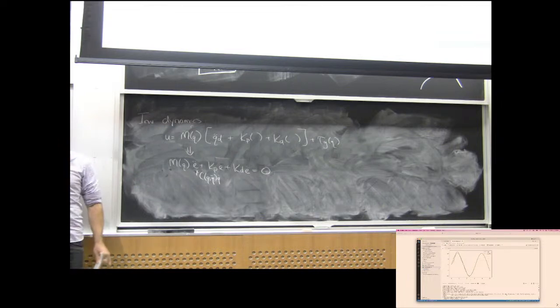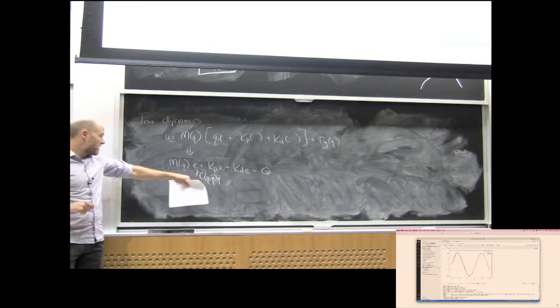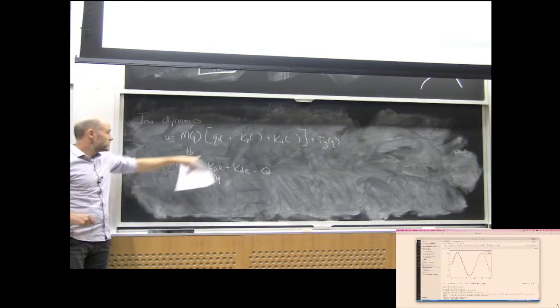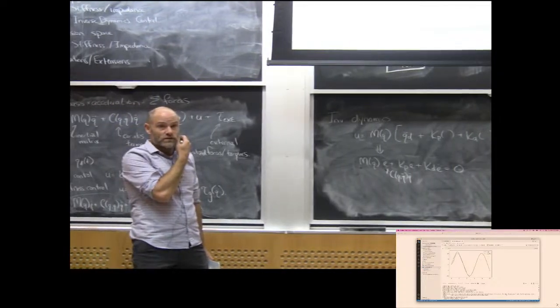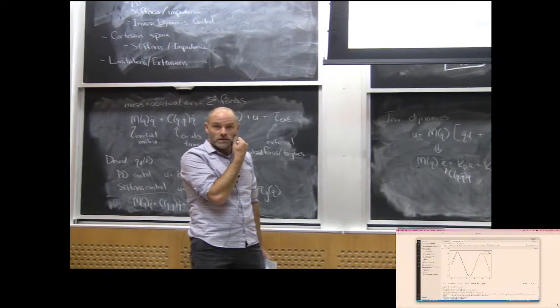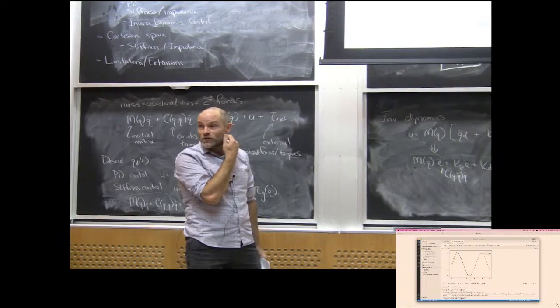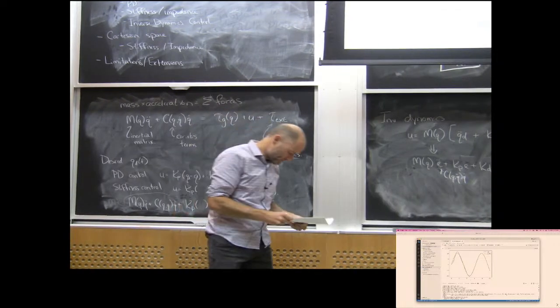If you had a torque-controlled robot and you wanted to do extremely accurate trajectories, then I recommend sending in the q double dot feedforward. I think it's only doing first derivative. It could be taking two finite derivatives, differences of my q command. But I don't think the advantage is there when you've already done a lag. So I suspect it's not.